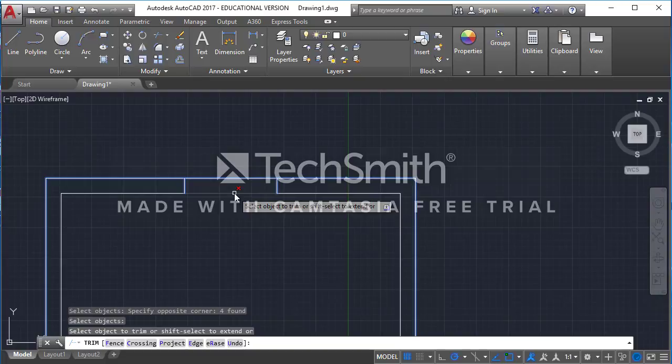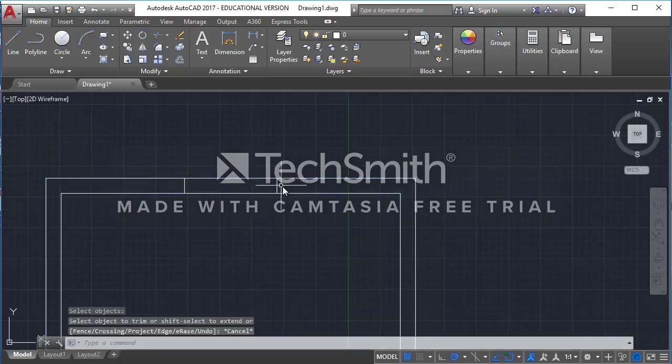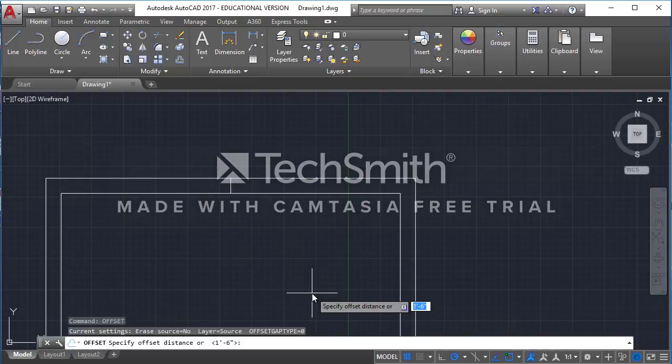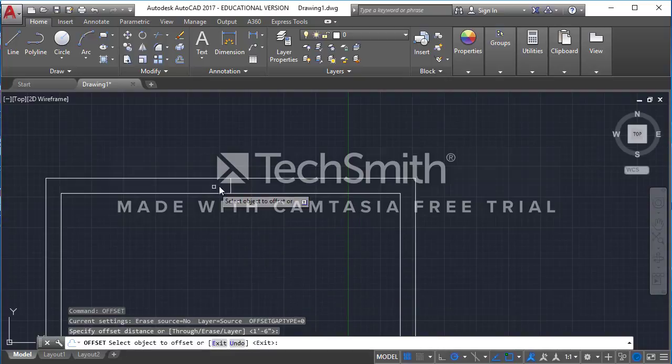Okay? Yeah? You get the lines to go perpendicular. Every time I offset it, it wants to add another layer around the border. Oh, how did I get this line right here? I drew that line in. So you're offsetting the original building footprint line that we created. You're going to want to go through and add these lines, so you probably have something that looks like that, okay? I just used the line tool. I snapped to the middle of that wall, and then I offset that line 1.5 feet on both sides.